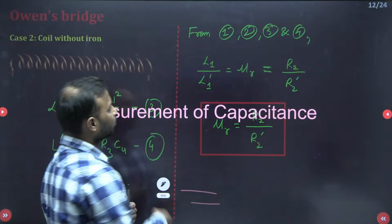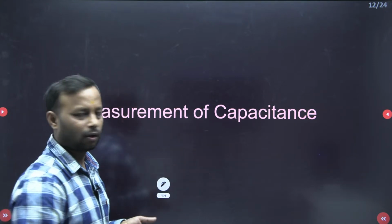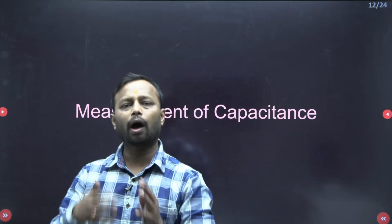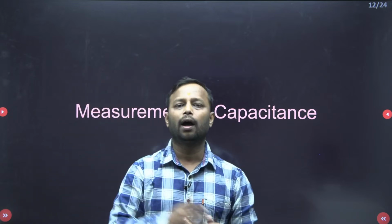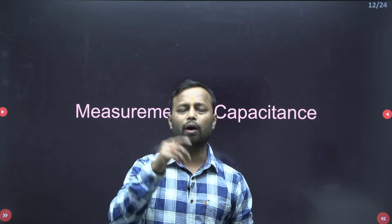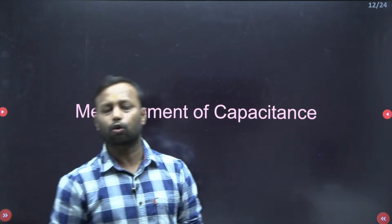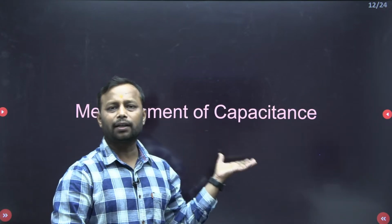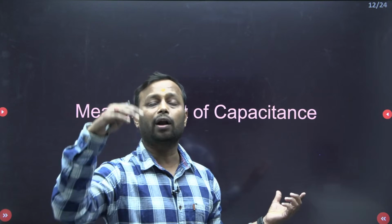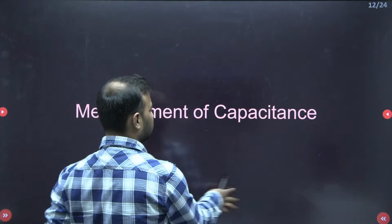Okay, let us move on to the next topic, the measurement of capacitance. Here again we are going to find the unknown parameters R1 and C1, and in this we are going to measure the dissipation factor, not the quality factor. The dissipation factor is the reciprocal of the quality factor, but for capacitance we always measure the dissipation factor, meaning the amount of power or energy dissipated. Let us see how we calculate.